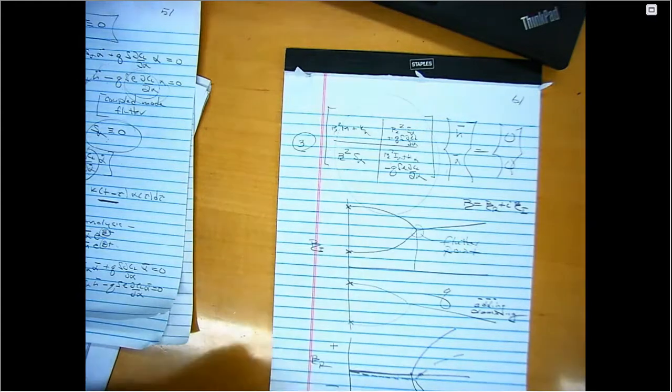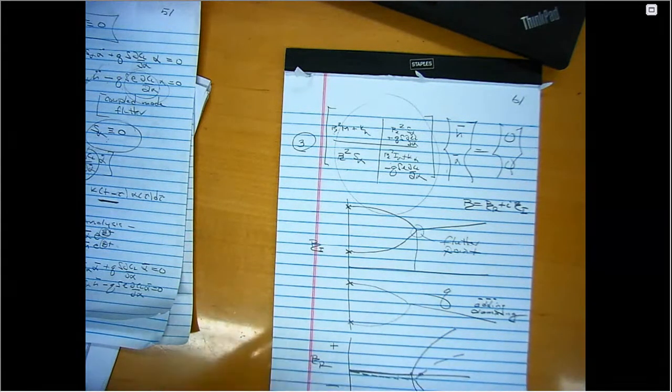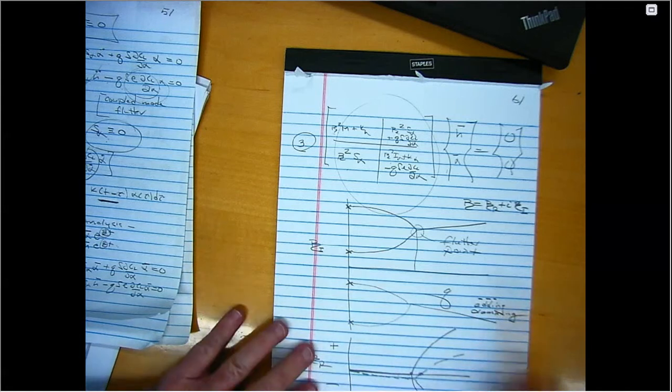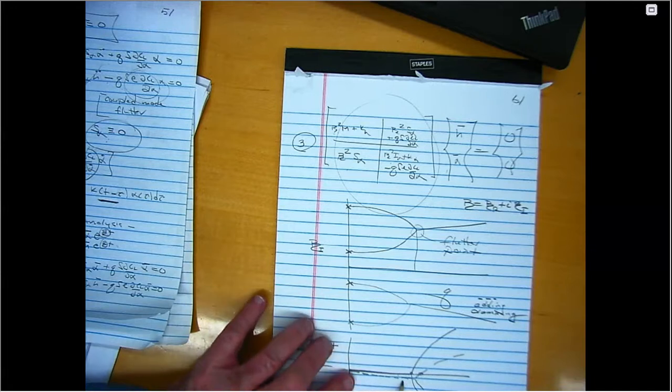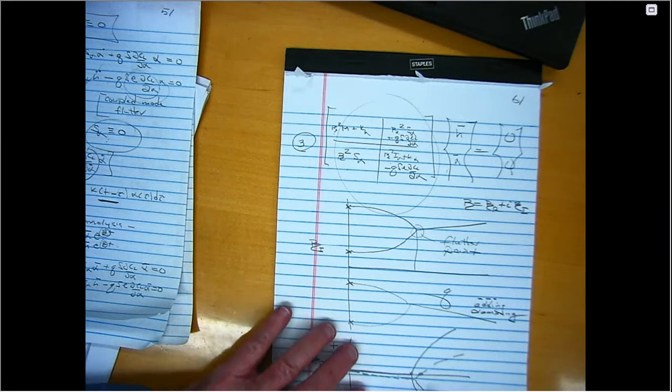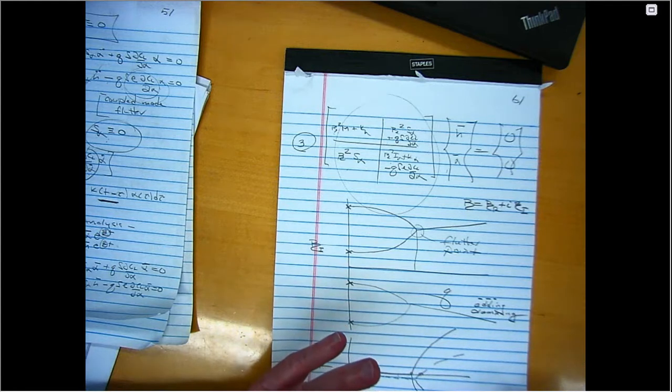If it's single degree of freedom flutter, what happens in the turbulent regime? These frequencies don't come together. These frequencies tend to just pretty much stay the same as Q moves out. But the damping changes. It goes from being slightly in the stable regime to slightly in the unstable regime. And single degree of freedom flutter is notoriously more difficult to predict accurately because we're talking about small stable levels of damping that convert, at some value of dynamic pressure, to small unstable levels of damping. And that's just harder for the aerodynamic theory to handle.